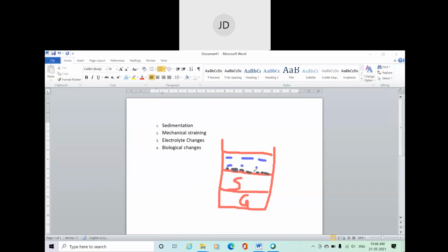Basically, the impurity present in water may contain very small organic matter. Then nitrogen, phosphorus, iron, manganese, etc. can be present as impurity, and they will be stuck in the top layer and make a biological film. Actually it is a layer of impurities, and basically it is known as biological film.